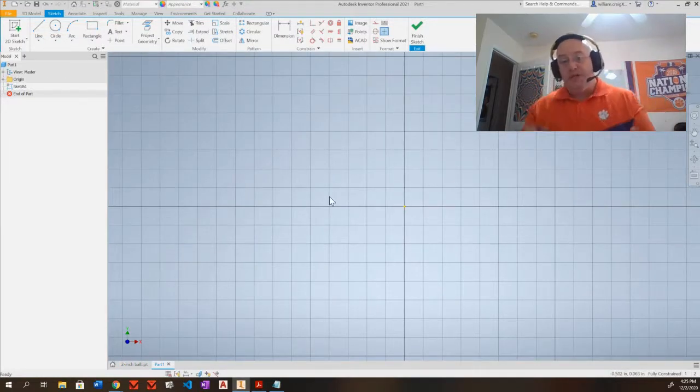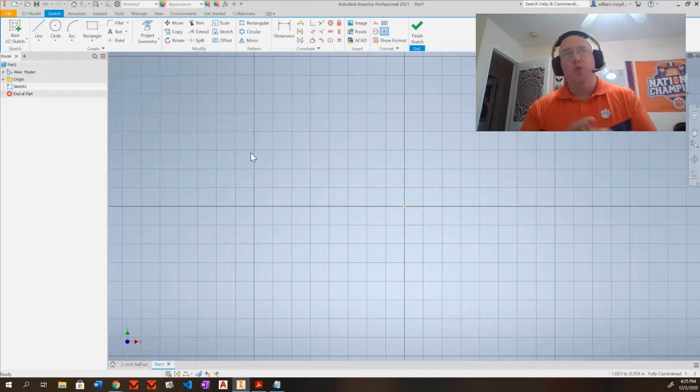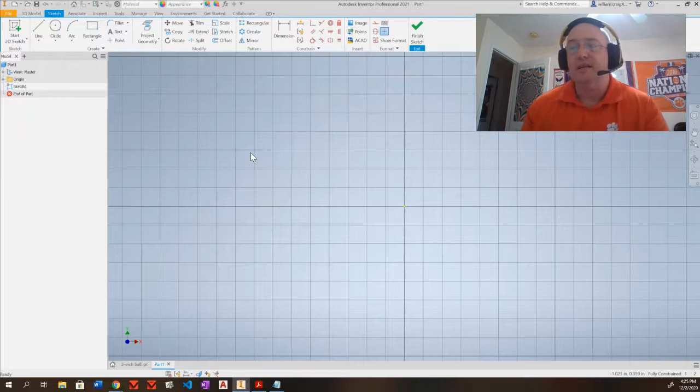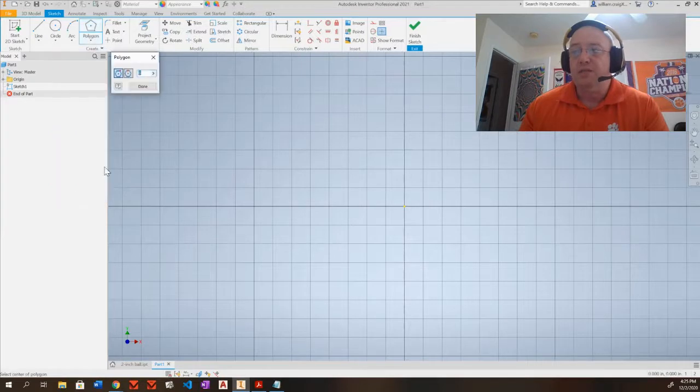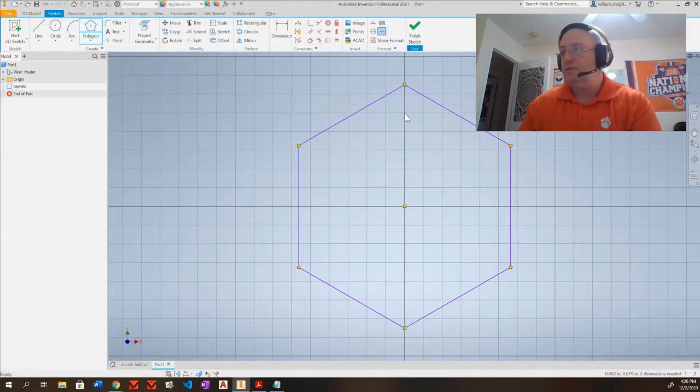So the first thing I want to do in here is build the head to the bolt. We're going to do a 1-inch diameter post to this, and we're going to put a 2-inch head on here that has a hex head with a tapered edge. So let's go ahead and do the head first. We're already in a sketch. If you have rectangle in here, grab the drop down, grab polygon. We're doing a hex head, so it's 6-sided. I'm going to come right here in the middle with my cursor, so I now have the green dot. Lets me know I'm right there in a lock-on spot, which is the middle of this. I'm just going to click and press escape.